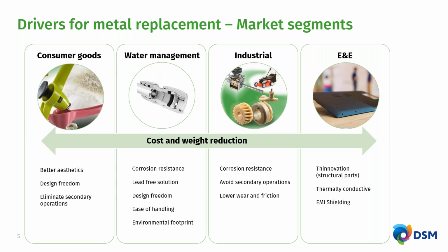chose for today's webinar. Across all these 4 segments, cost and weight reduction is a key driver for metal replacement. If you look specifically at consumer goods, it could be better aesthetics or design freedom that plastics provide over metal, which can be a major driver, or elimination of secondary operations like coating or painting. In case of water management, some of the key drivers are corrosion resistance offered by plastics. It gives a lead-free solution, ease of handling and installation. And in case of industrial segments, it could be low wear and friction or avoiding secondary operations together with corrosion